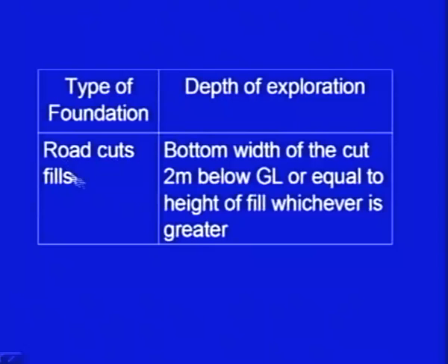If there are road cuts and fills, then the bottom width of the cut, 2 meters below the ground level, or equal to the height of the fill, whichever is greater, should be taken as the depth of exploration. So, this was the discussion about the exploration depth, and as I told you, these are only guidelines and there is no fixed answer. The decision will vary from site to site.